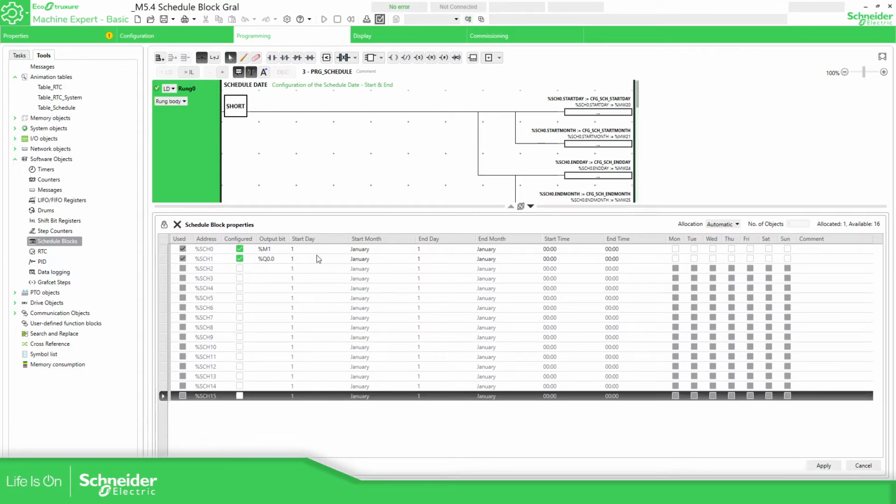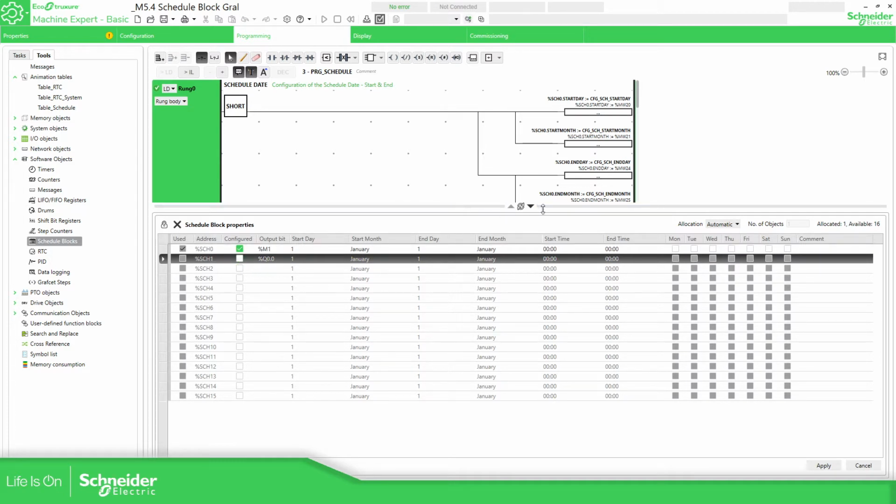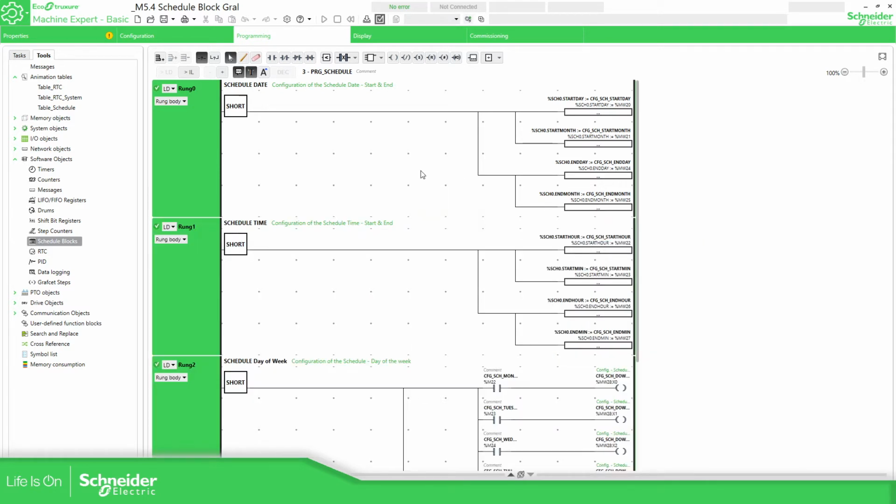There we go. So we have the possibility to fix the date and time for the action that we want, or link the instance value that we want to a variable, as I show you here. In this example, I just configured it to assign %NW variables to the instance, for example, to the start date, end date, and month also, and then for the time, hours and minutes to start and end.